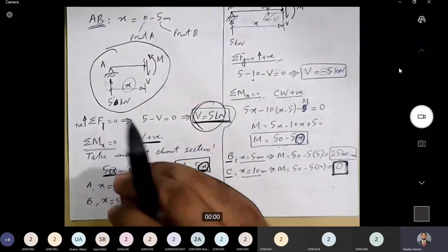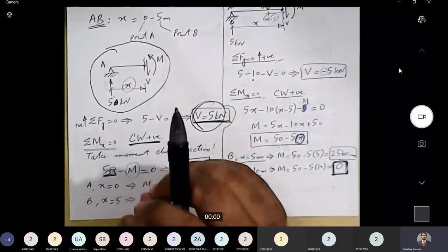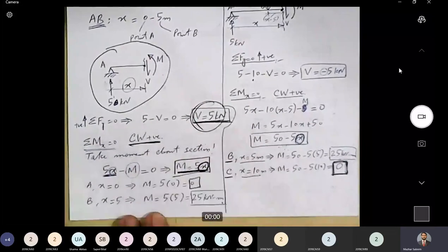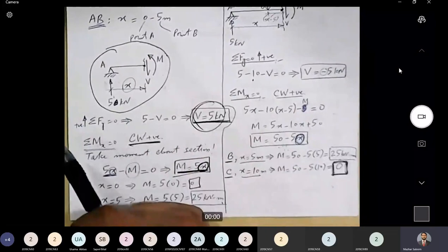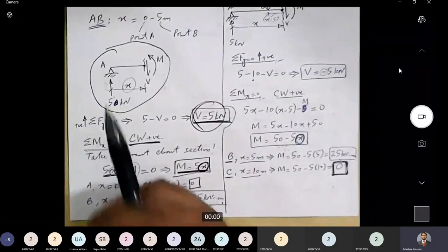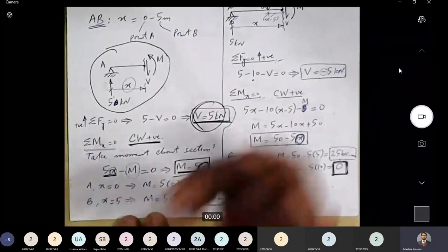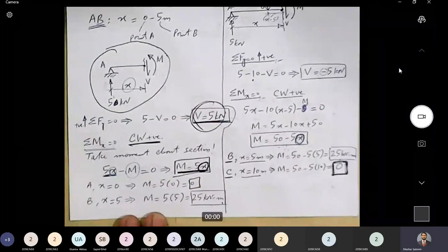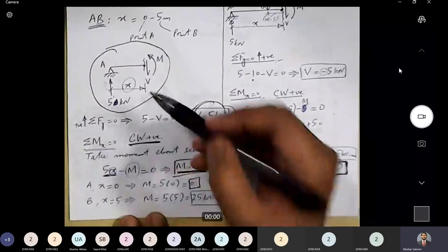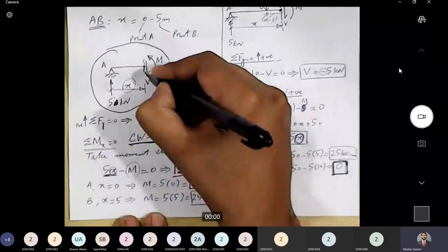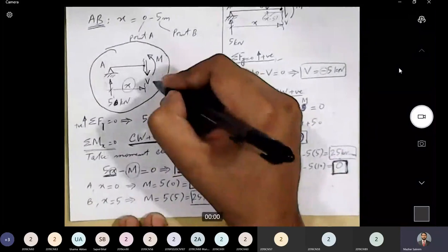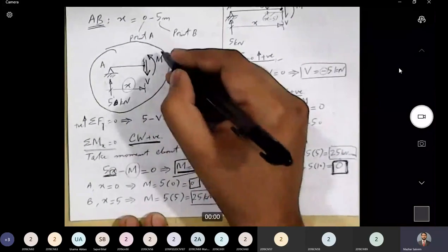and these forces are not visible, but when we cut a section through the beam, then these forces get exposed. So whenever you cut a section through a beam, you need to mark the shear force and bending moment, and these forces can be marked in any direction, but in our case, we will be following one convention, that we will always mark shear force in the downward direction and we will mark bending moment in the counterclockwise direction.